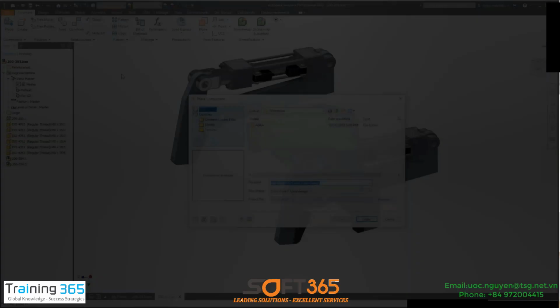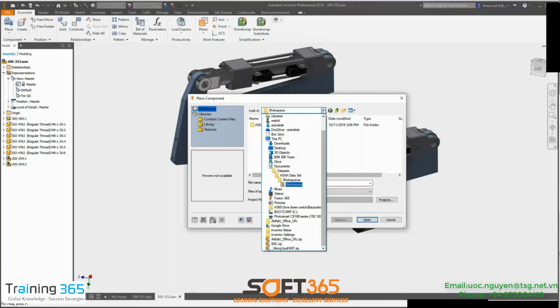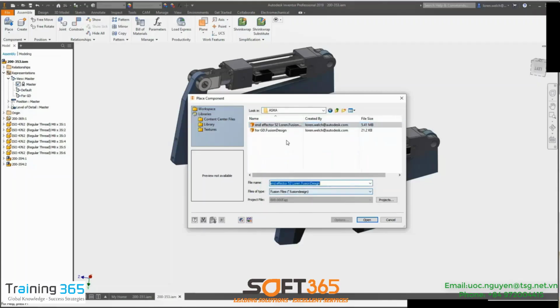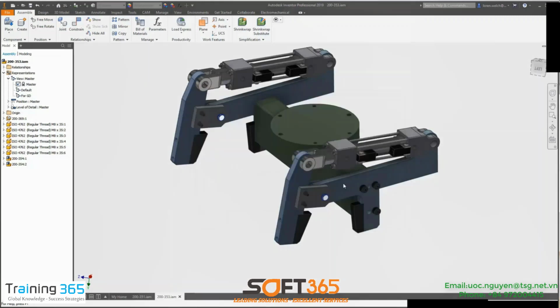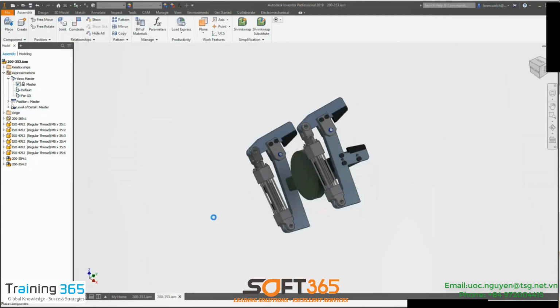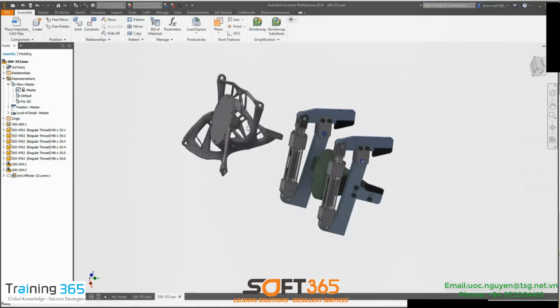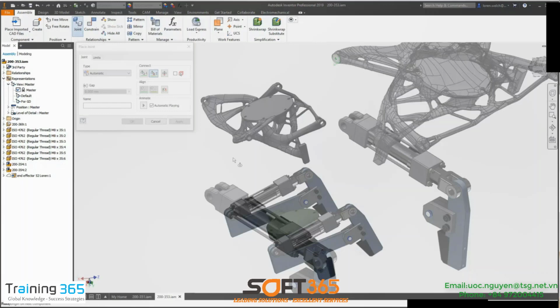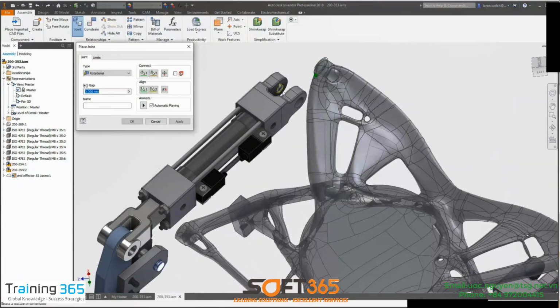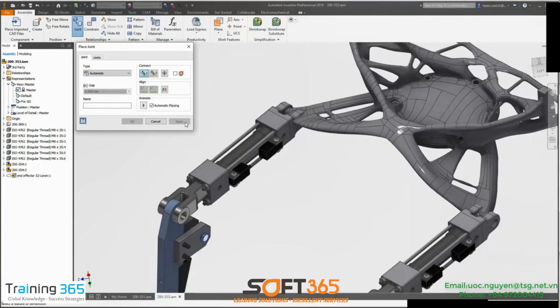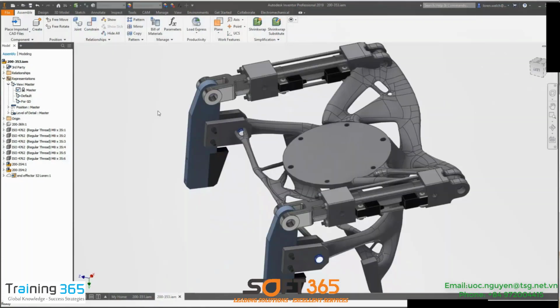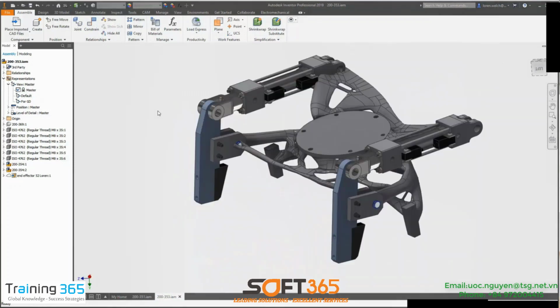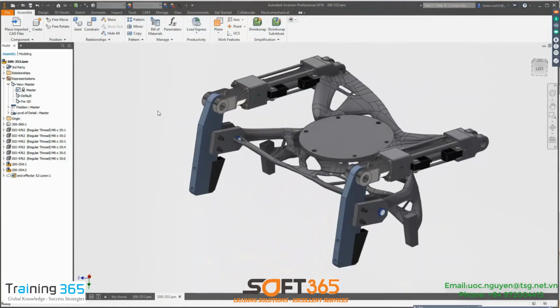So now what we'll do is we're using the Connect Desktop and Fusion Team, or desktop connector. We're going to go ahead and bring that in as an AnyCAD piece into our Inventor assembly. And just like with a standard Inventor part, I can use joints or constraints, get it all constrained up. And there is a quick example of a workflow going from Inventor using the desktop connector and the generative functionality, and then bringing it back through the same bridge using Inventor desktop connector back into Inventor.